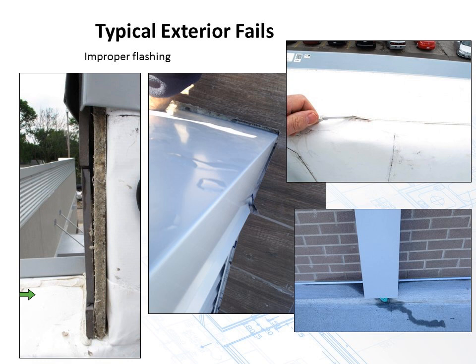Here's an exterior on, again, one commercial project. They just stopped the tile with a cement board over the waterproof membrane here. You can see the top of this cap doesn't really drain all that well. I mean, this is overlapped. You can see where there's no sealant where the cap flashing goes up against the tile, nor where the tile butts the building. The roof membrane has a tear in it. This comes up over the parapet and then right underneath that flashing.